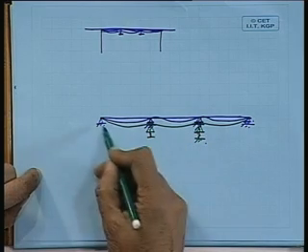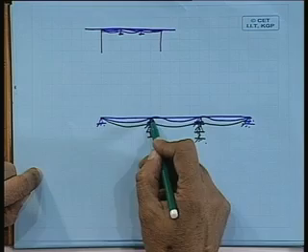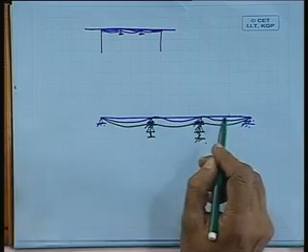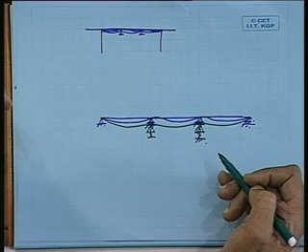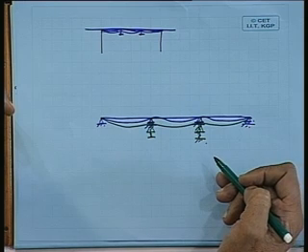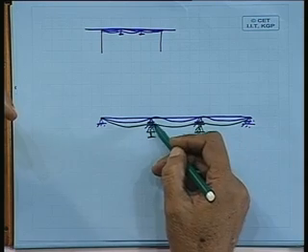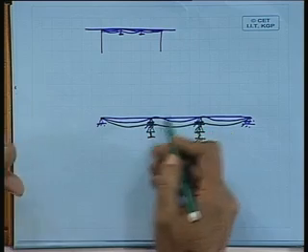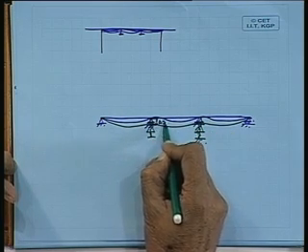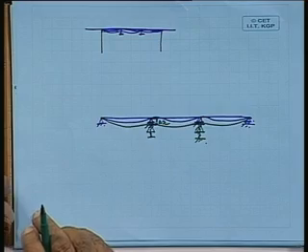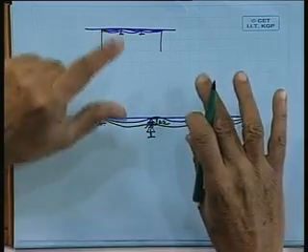So, you can have a sinking support or you can have a rigid support. Basically speaking, the girders should be treated as a sinking support, and find out how much will be the deflection here first. So, this will give you a true picture.